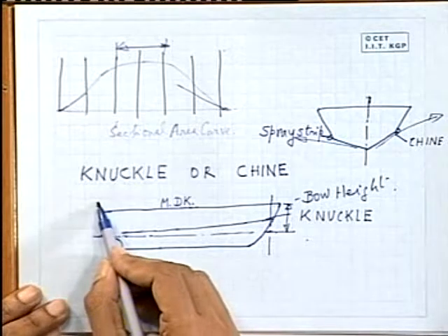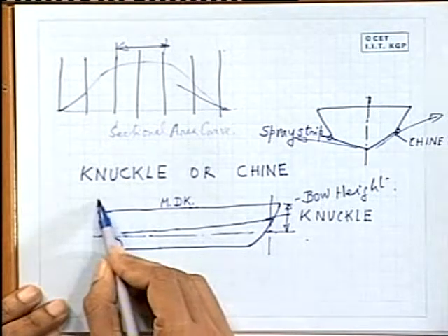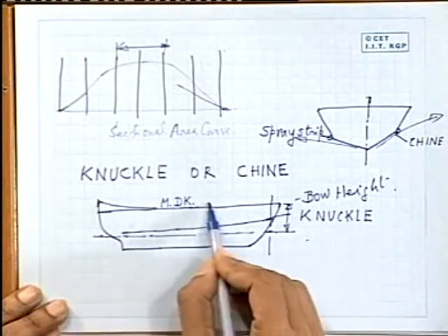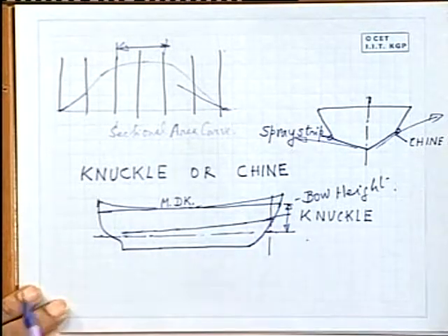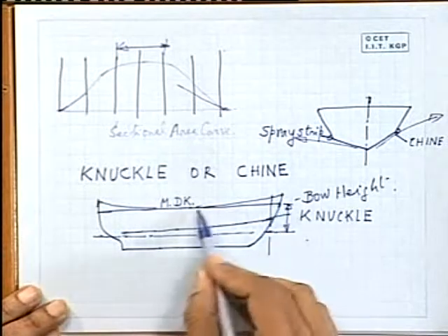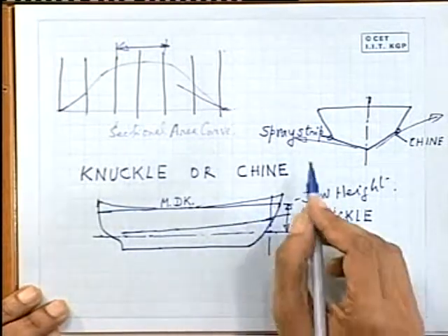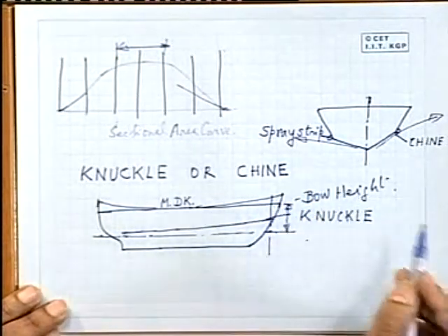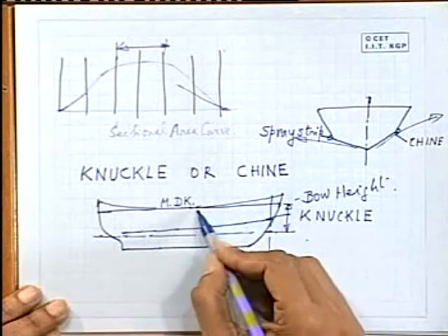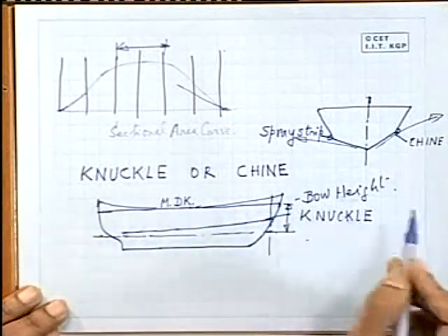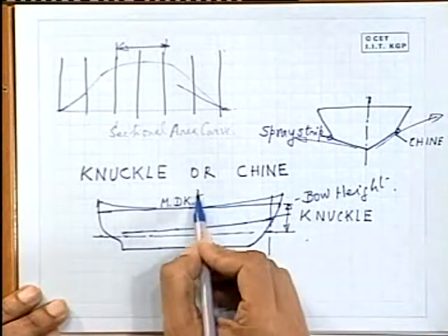the deck is also given a shear. Shear also gives more height to the main deck. But this deck shear nowadays you can find that most of the big ships rather avoid, because then again they have to bend another plate to this curvature, and the construction problem is there.